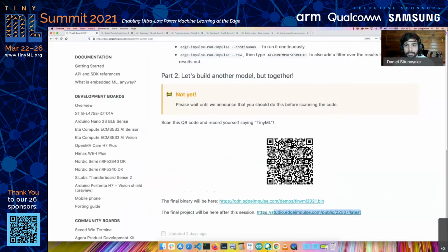So imagine you've got a model you've trained and you want to determine whether there's rain falling based on the sound currently. Usually when it's raining, it rains for at least a few minutes. And so you probably only need to wake up and collect some data once every few minutes. You don't need to have the device constantly on, constantly collecting and running inference. Whereas if you had a device that was determining whether a bird is singing, birds usually only sing for a few seconds at a time. So maybe in that case, you do need to have a constant cycle running with inference running all the time. So it's very dependent on your particular application.